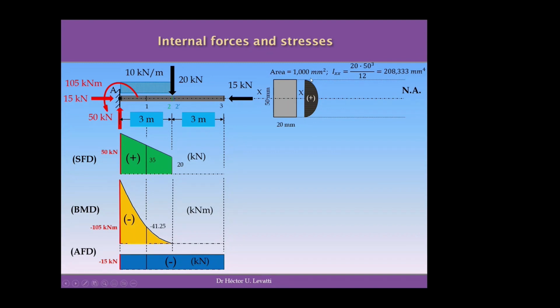Now you will see why we have calculated this moment of inertia and when we use it to establish values of stresses. In order to calculate the maximum shear stress, we need first to know that the maximum will be in correspondence with the neutral axis. So we are interested in defining the area in green, which you can see on the screen, that is on top of this neutral axis. And we need to locate the center of this green area as well, because we need the distance from this centroid to the neutral axis.